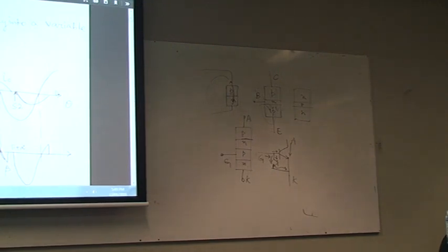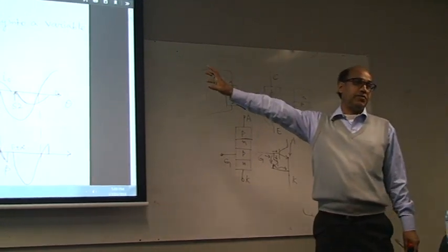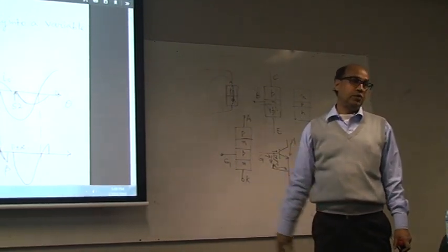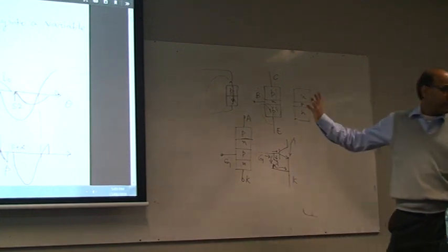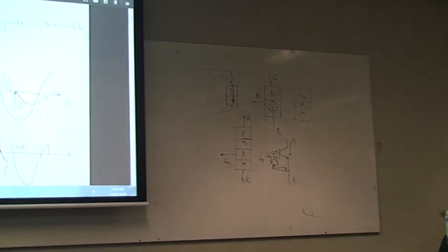In this circuit, where is the gate signal coming from? Is it just a voltage threshold? You do not need to give a constant voltage, you can give a pulse. That pulse would come from the AC, and once it gets through the threshold, it will open the gate. Yes, you have to design a separate circuit for that, to give that DC voltage. Once it starts, it will continue to conduct.